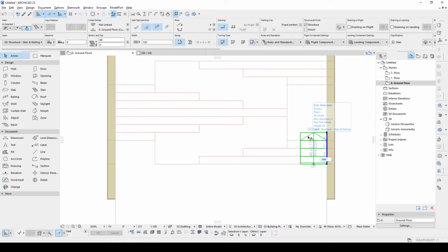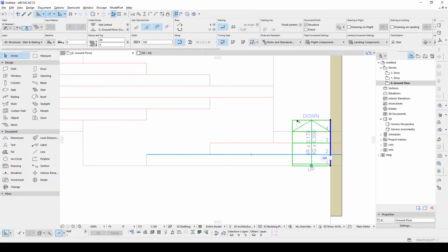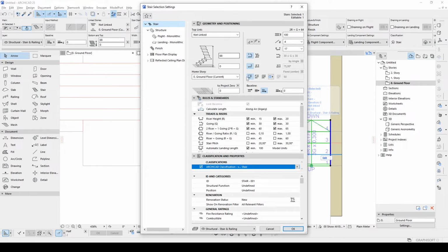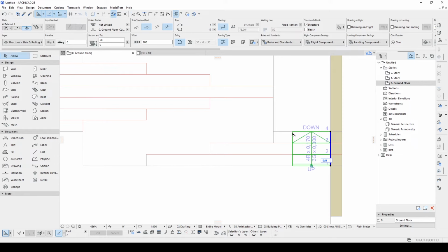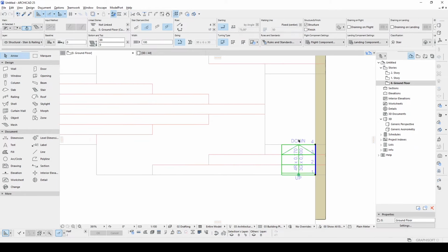Like so. As you can see, it reaches the wrong direction. So we are going to fix that in the settings. To fix that, this setting will be start with riser, and this setting is end with riser. So we are going to get rid of the unwanted riser with the fourth one.